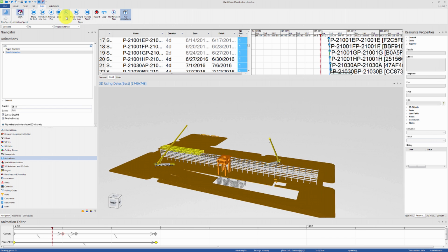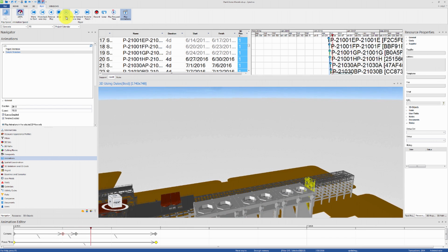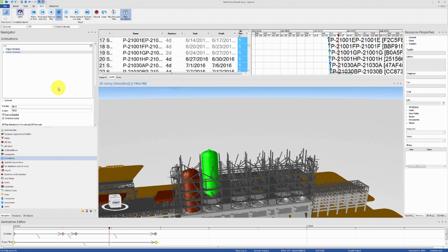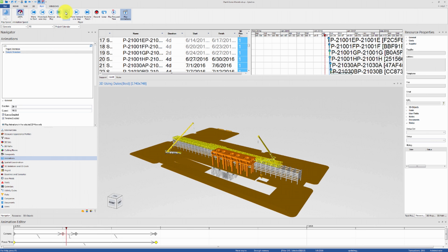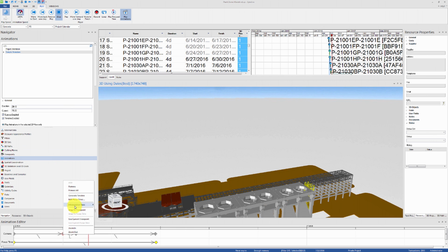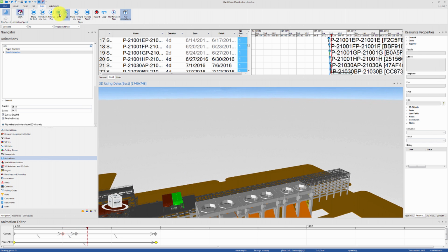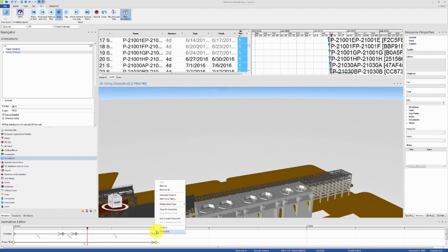The new animation looks nice, but we may want to try a different interpolation type between the 2 fast camera movements. Let's try a step interpolation. Notice how the camera now jumps between these 2 keyframes from one view to the next. Now let's try a curve interpolation type and see what happens. Note that you can also use a custom drawn 3D path for the camera movement, or use a turntable effect.